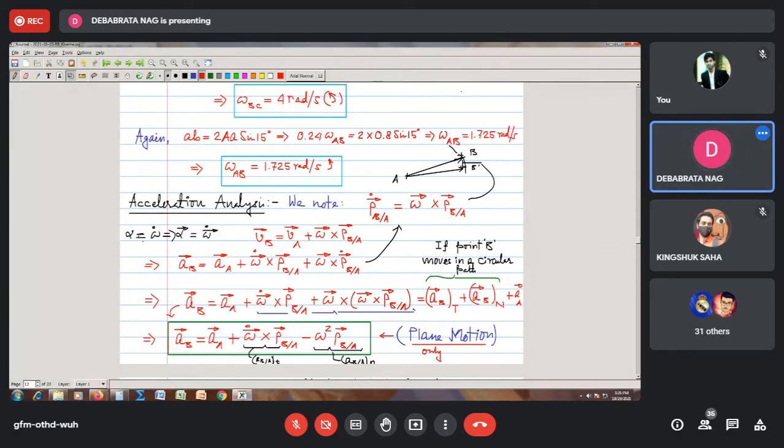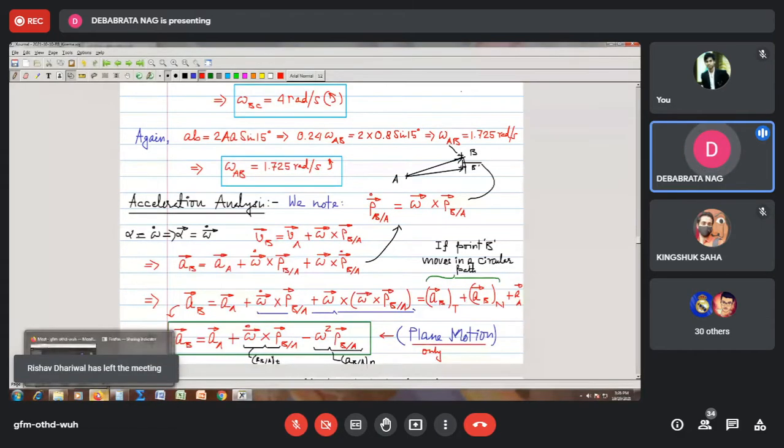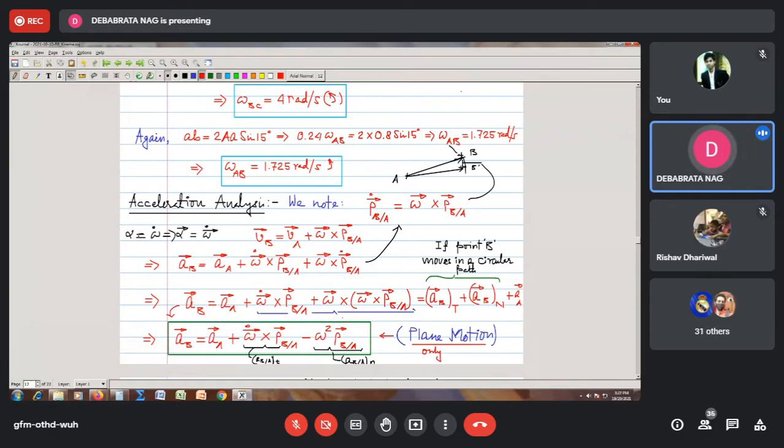So we note that the last term, omega bar cross omega bar cross rho bar B relative to A, can be simplified, particularly if one follows the vector triple product. One can simplify this equation to this format. This is called the tangential component of the acceleration, and the last term is called the normal component, and you see this negative sign. The negative sign indicates that the normal component of acceleration will be directed towards point A. This is the direction of rho bar B relative to A, this vector.